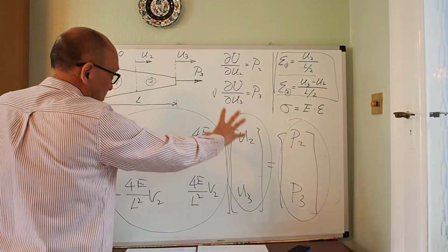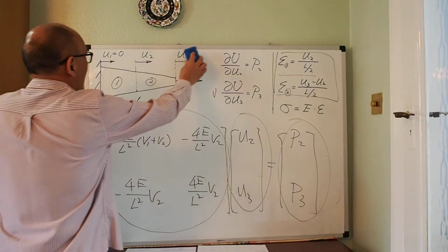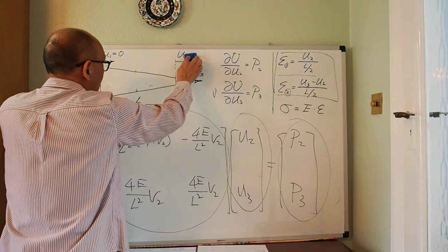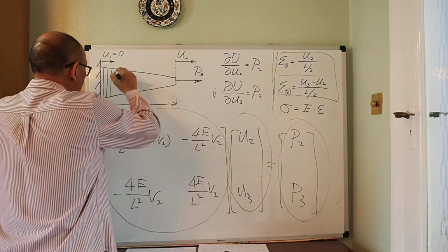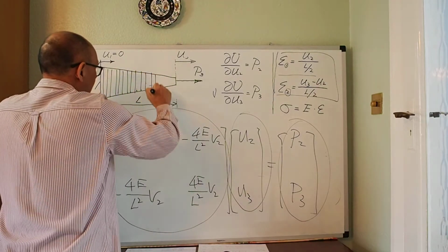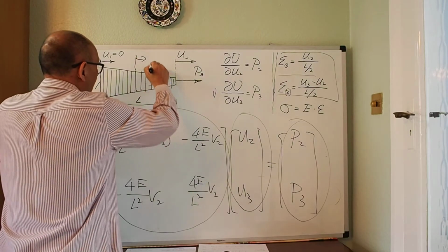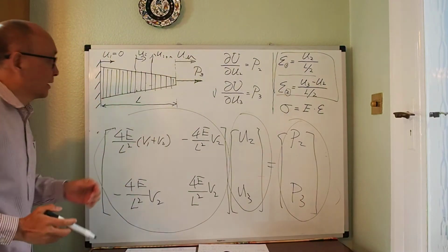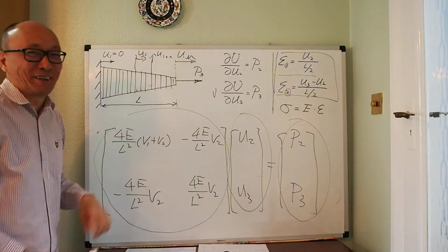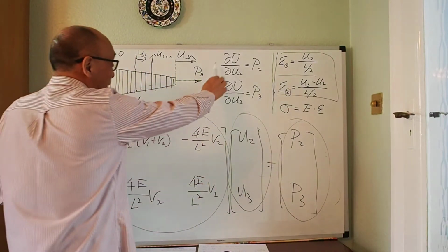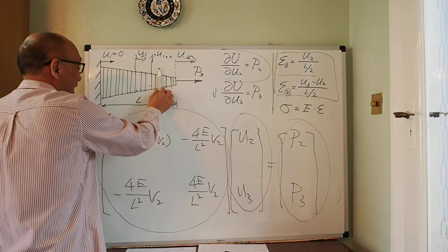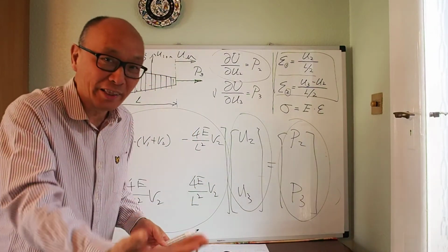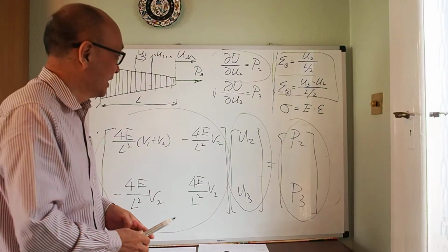To make this calculation more accurate, what you need to do is divide it into many small elements. And then each of them has a displacement, so u_i, up to u_n. So you need to divide the bar into a lot of elements. But it's not a problem, because then you can apply your Castigliano theorem anywhere you wish, at all these sections. Every time you add a new section, you add a new unknown, but you always have a new equation. So you always have enough equations.